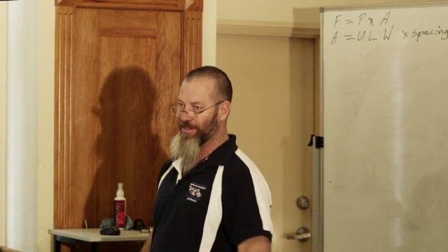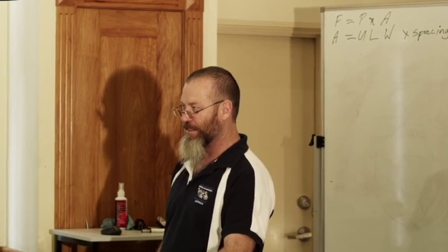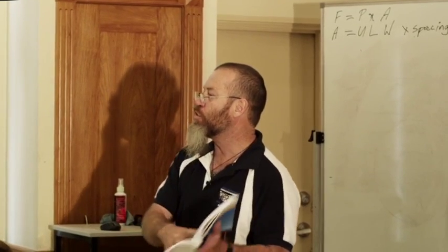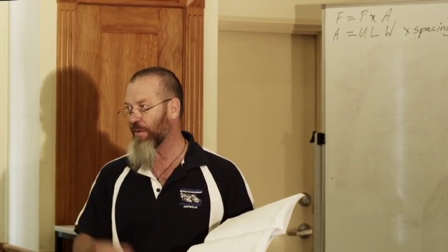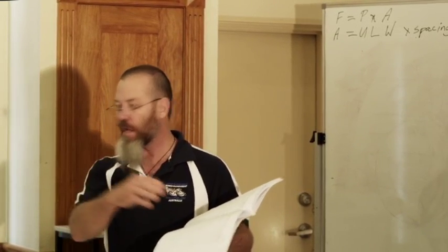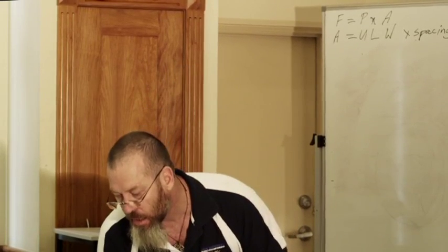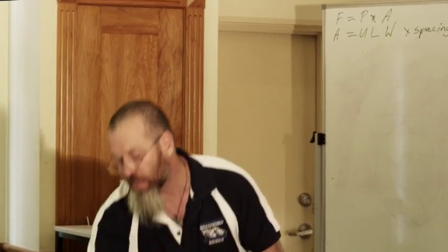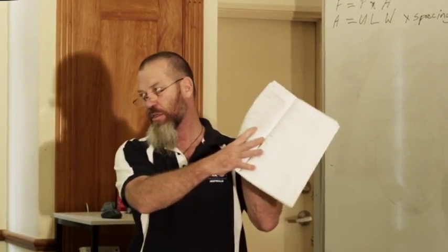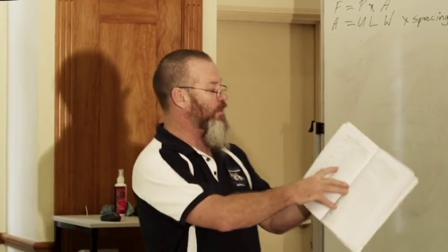Now that's a mistake in itself. There's a typo there. Cross out the word screws and write nails for a start. So you can only use 2 nails in a 75mm batten. So we can't use that connection. We have to go down. So you come down here. 2006, doesn't it say nails? Yeah, it says nails in the old standard, but it's screws in the new standard. This is mistakes, I told you. It was a pretty average document.